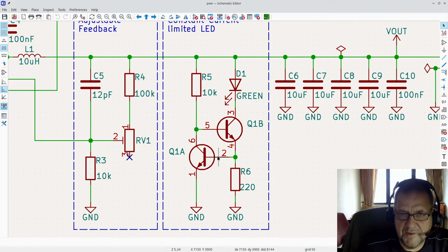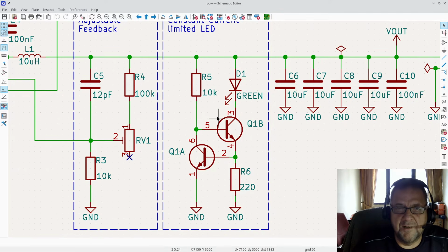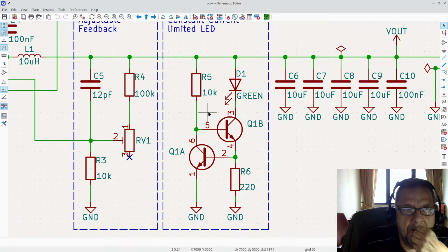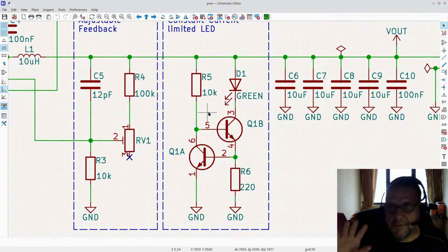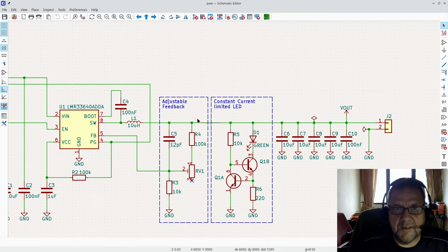Now, transistors, you know the voltage between the base and the emitter. So there is 0.7 volt here. So by 0.7 volt using Ohm's law divided by 220, you can calculate the current that is going to go through this one. So it works. I actually did a simulation of this as well. Can't remember where. I might show that later. But it works. And that is about it.